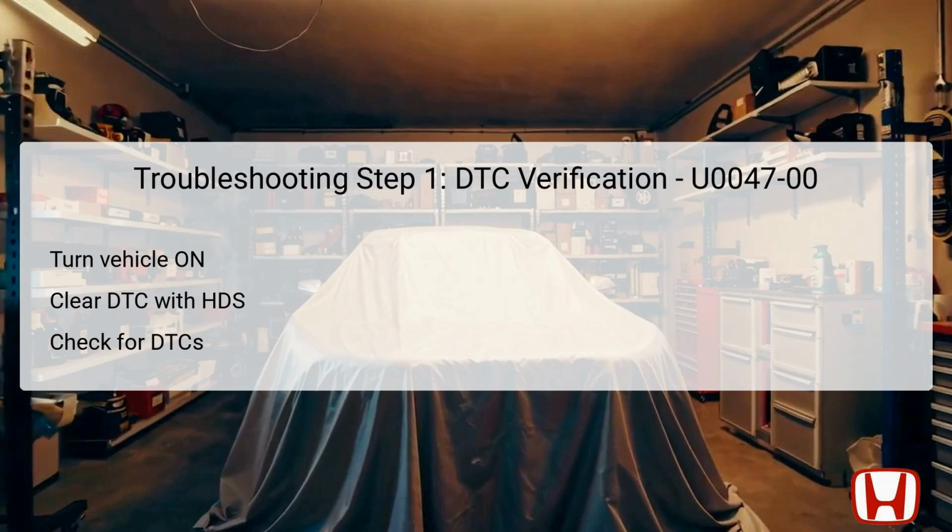Finally, check for DTCs once more using the HDS to see if U0047-00 has reappeared. If it is confirmed, proceed to the next steps in the troubleshooting process, indicating an ongoing issue that needs to be resolved.